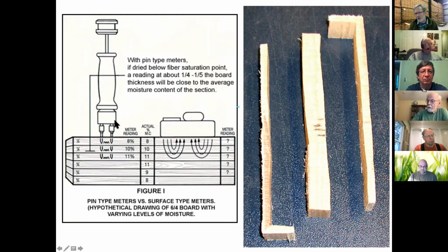If you want to do an oven dried slice test to tell you what the difference between the outside of a piece of wood and the inside is, what we call a shell and core test is something we typically do. So we take this to a bandsaw, I cut out this little L for what I'll call the shell or the outer part of the piece of wood, and I measure this and this separately from the center. And then when I dry them, I measure them separately again, so I can calculate the moisture content of the outside of the wood, as well as this piece that was on the inside, right? And that'll tell me what the difference between the outside and the inside is using the oven dried method.